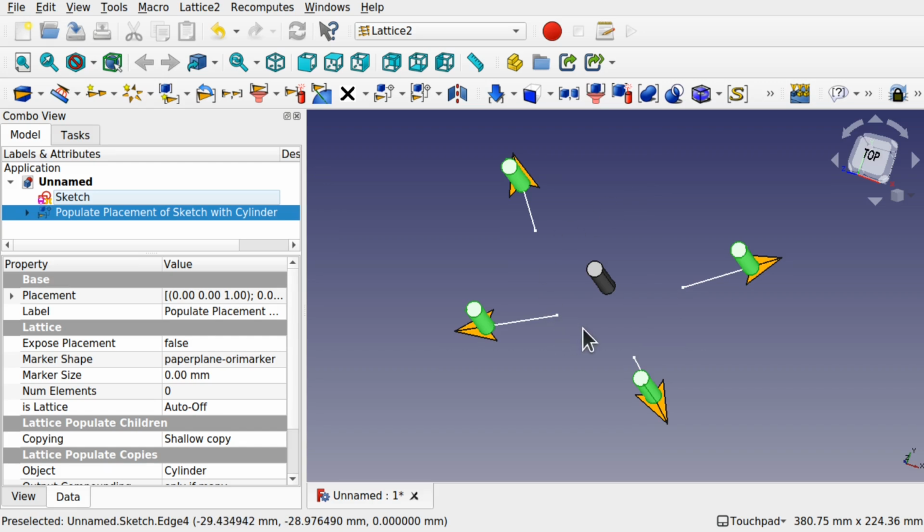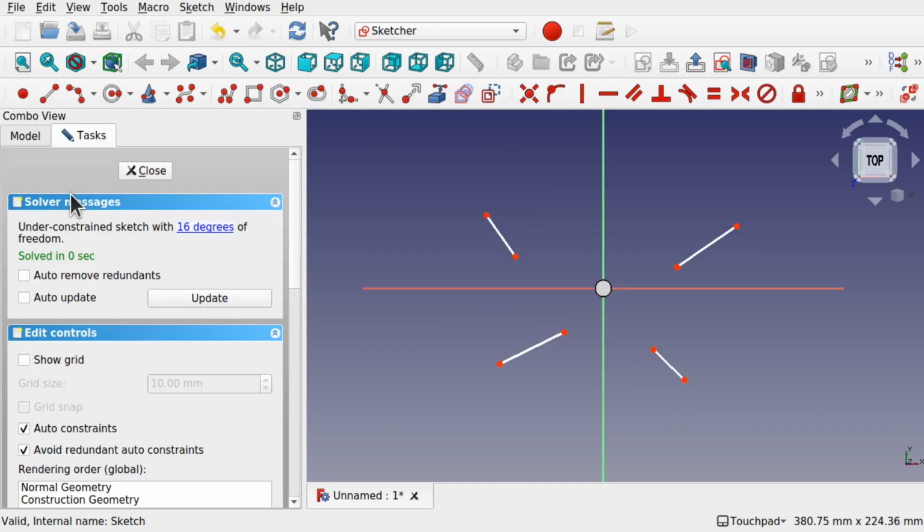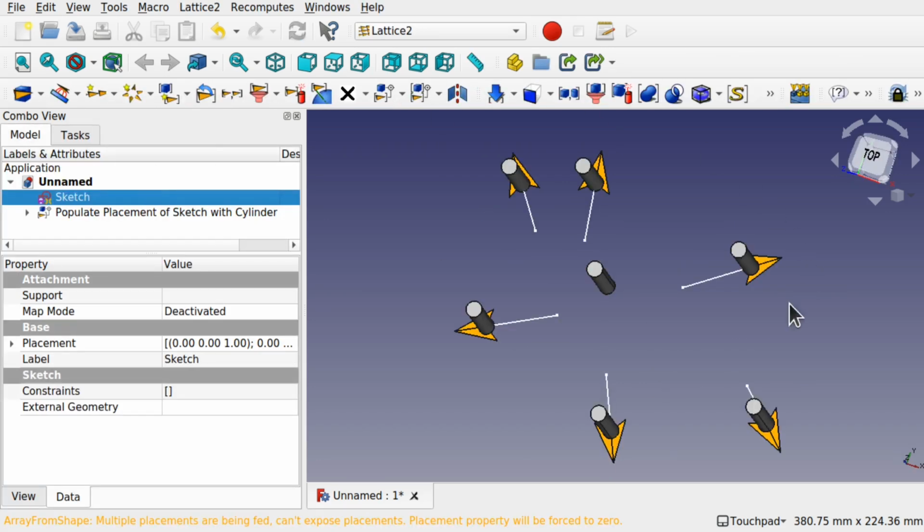Now, the other videos I've said about placement, we can actually place a placement on here, and we can do that with this. We'll get to that in a minute, but that's how you add those two there. If we change this sketch and add, say, another line or another couple of lines and hit the right mouse pointer or hit escape and say move this one over here, then these will be updated with those elements added and new placements. Look at the populated copies.